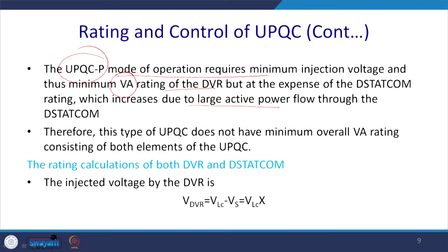Therefore, this type of UPQC does not have minimum overall rating. The DVR rating may be low, but the D STATCOM rating is high. So, it is not optimized.